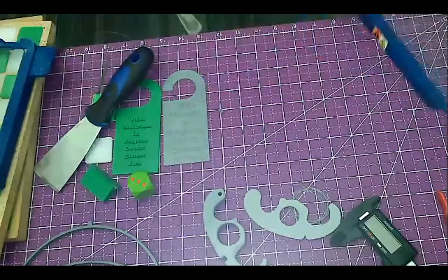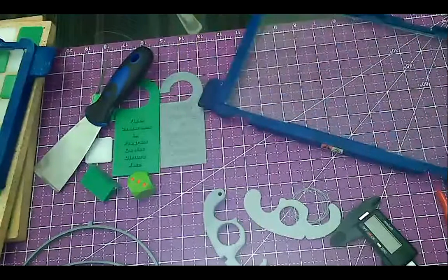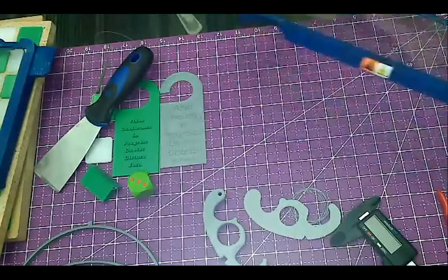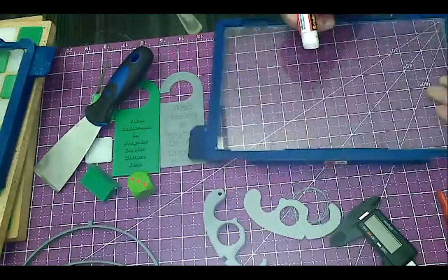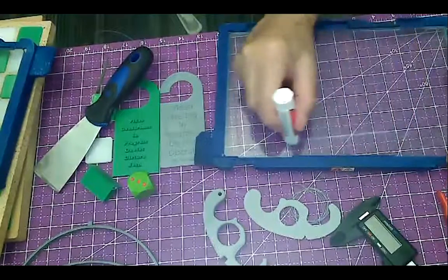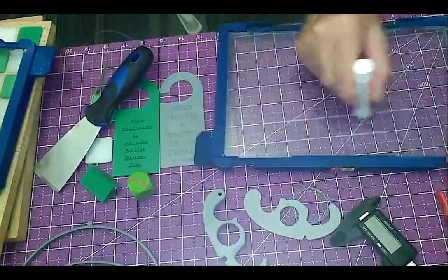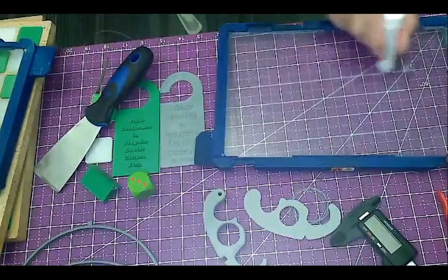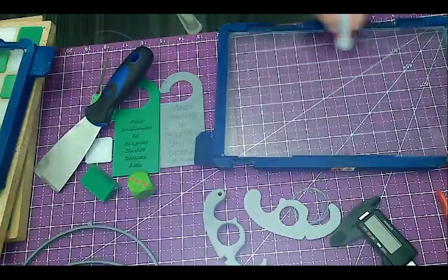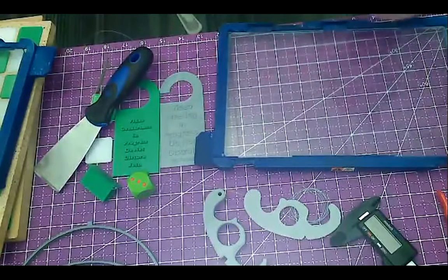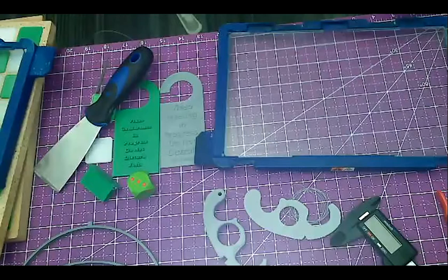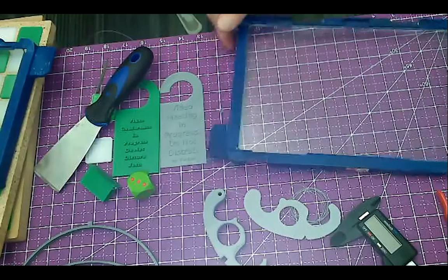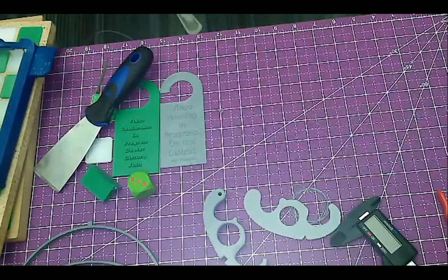We get our build plate, and the orientation of that was, I would say, right about here. And as you apply the glue, just a light coat. What happens if you put too much glue on it, Joe? It gets really messy, and it doesn't necessarily help adhere it. It bumps up against the nozzle.